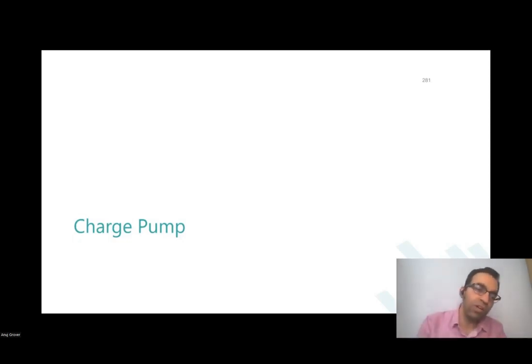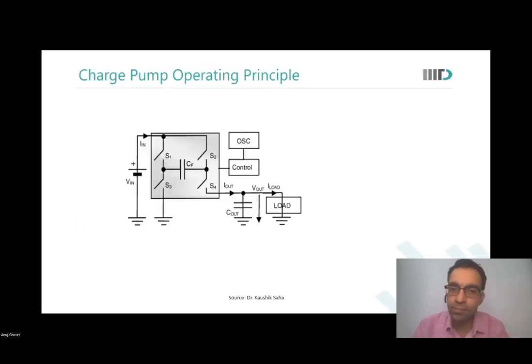Now, those of you who are working on the negative word line, negative bit line driver, can you sense something? What could a charge pump look like? Some circuit with capacitor. There is a capacitor which stores charge, and then that charge is pumped onto another capacitor, due to which the voltage between the plates of the other capacitor rises very much. The extra charge has pumped up the voltage. So this is how it would appear.